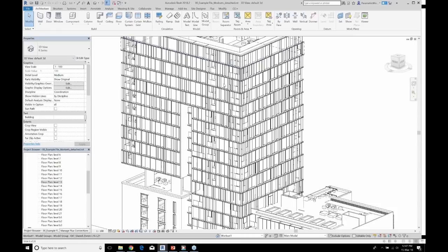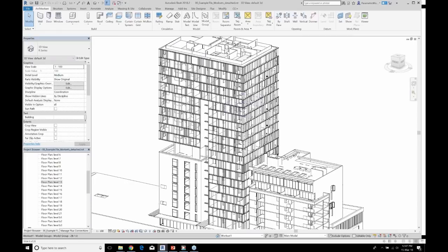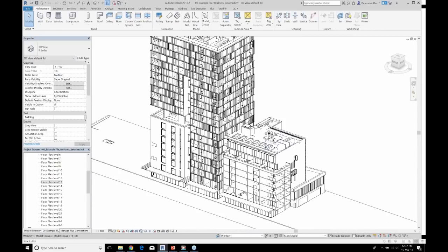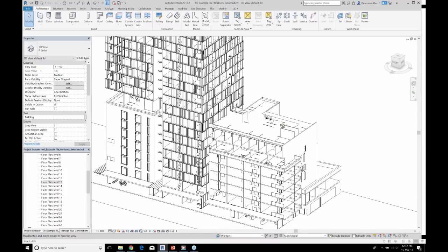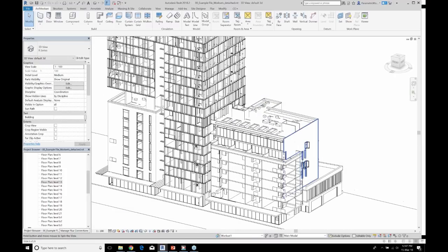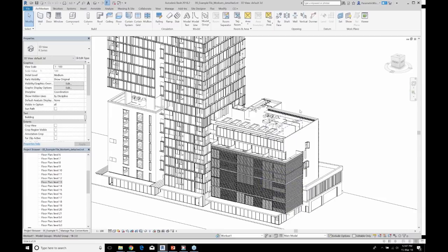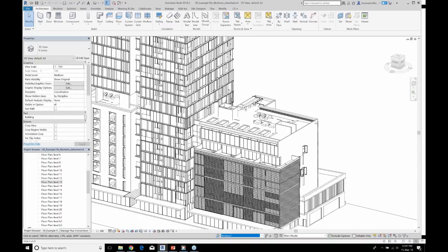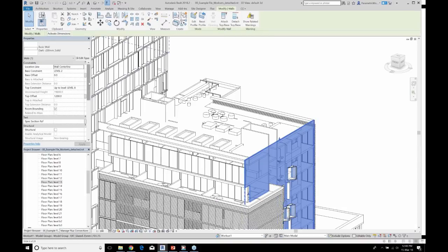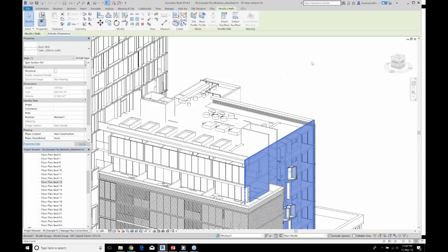So I might just flick over to Revit. So this is the project, and I just want to show you the current state, show you that there's nothing hidden up my sleeves like a magician. I've enabled worksharing already. So we've got our standard Workset 1 and shared levels and grids. Everything by default is going to be on Workset 1.